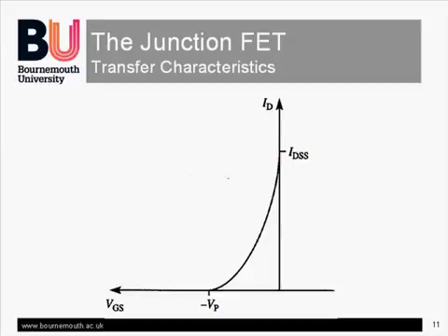As the characteristic is nonlinear, we can represent the small signal gain, or transconductance Gm, as the slope of the curve at the appropriate circuit DC operating point.